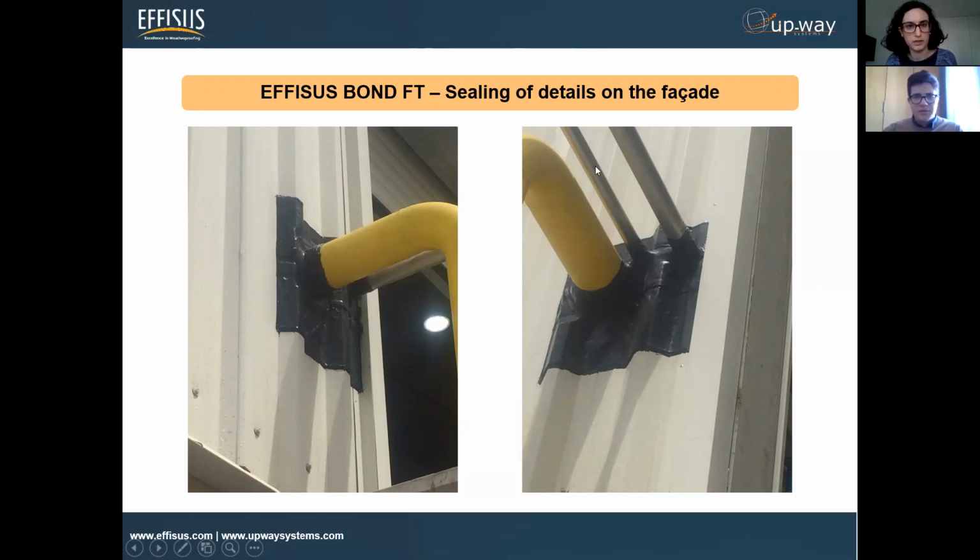It's important to mention the standard market solution. It comes to types of silicone mastics, which is all right. But again, since in most of these cases it's going to be total exposure, these materials will start cracking. In the end, it will not fulfill the goal of sealing this point because it will start leaking, of course. And then very high maintenance, which is quite simple. You just have to apply a bit, but then you do this over and over and over, depending on the cases.